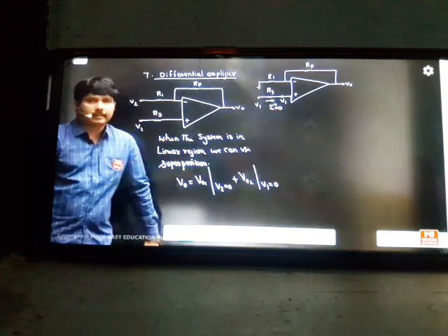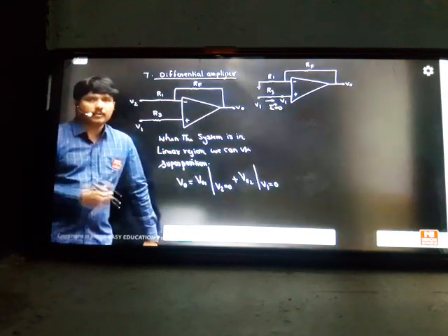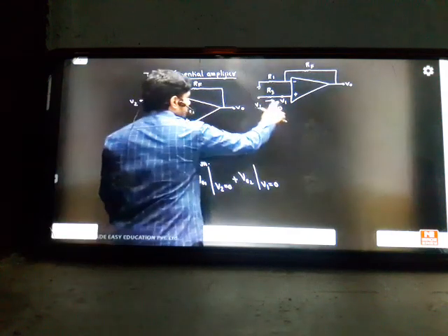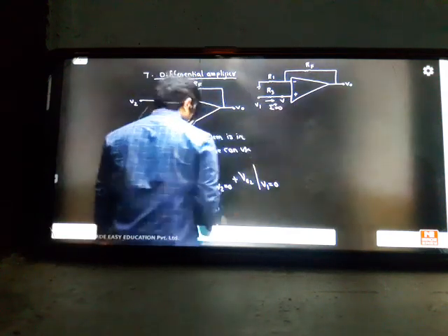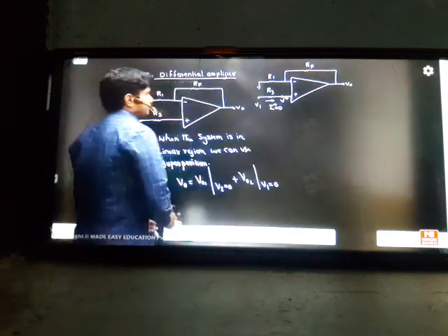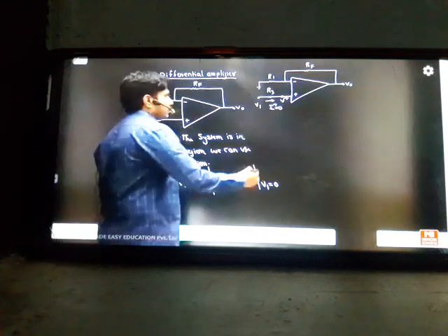So resistors in the exams, you may take them or not. We don't bother about the resistor because current cannot go into the op amp. That rule you have to apply. So this answer will be the same. Otherwise you can write it like this: this answer you take as V plus. According to the story, now we'll write the answer first. This is a non-inverting amplifier.